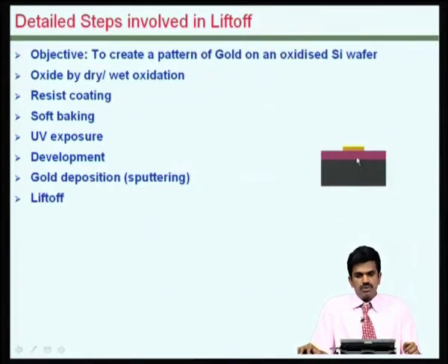If you were to do the same thing by lithography, after the pattern transfer we would be doing the etching of the gold. That would have required aqua regia and other chemicals such as iodine, for example, but in this case that is avoided.